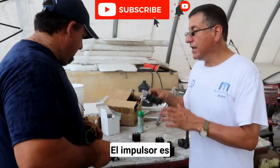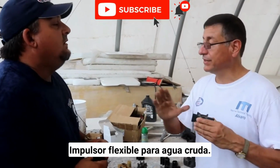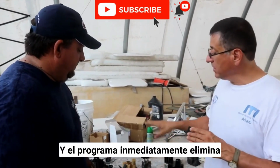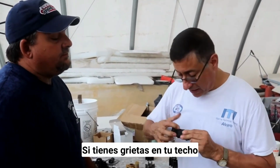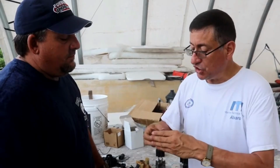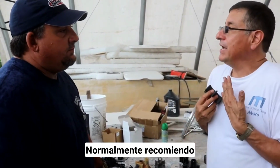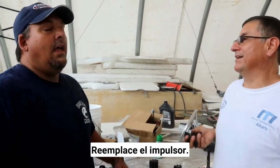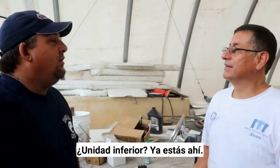The impellers are flexible impellers for raw water. This is mandatory in inboards and outboards. Absolutely. And the procedure, immediately after you remove the impeller, is to check if you have cracks and check if all the blades are in good condition. Normally I recommend, if you remove the plate on the impeller, replace the impeller. Because how many times do you spend removing the lower unit? You're already there. And this is not expensive.